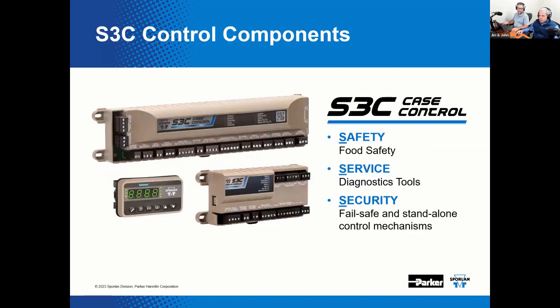Here's a brief refresher. Remember the S3C case control? What does that mean, John? That would have to do with safety, service, and security. Yeah. Now, some of the things we're going to talk about today is that in most situations, the supermarket owner would provide case coil specifications to the manufacturer, and that manufacturer or original equipment manufacturer would then pre-program the set points into the appliances. What do I mean by appliances? Refrigerated display cases. Yes, that's code for that, I guess, right? To allow for a quicker startup at the supermarket.